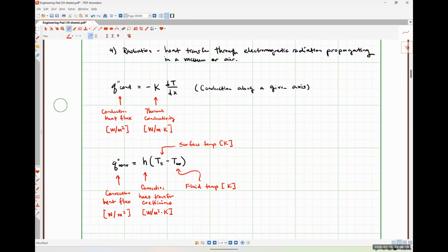The convective heat transfer coefficient is dependent on surface geometry, fluid viscosity, fluid velocity, and thermal diffusivity. And then I've got a little table that I found in a textbook for typical values for h. So that is just the temperature. That symbol collectively is the symbol that I'm using for fluid temperature. So T subscript infinity, the infinity doesn't mean anything as far as I know.